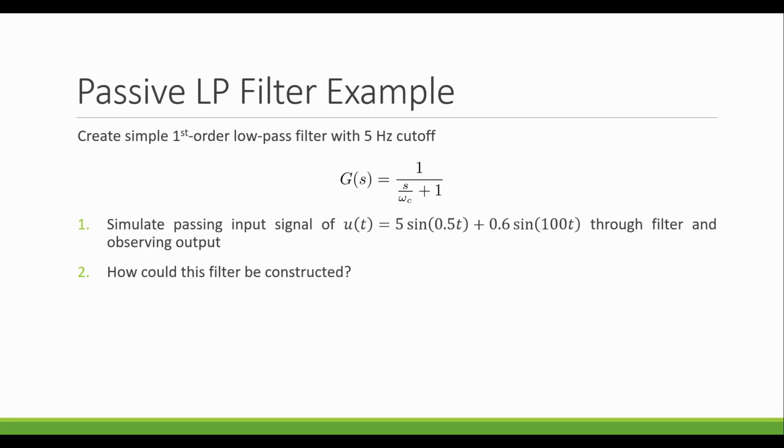A couple lectures ago when we talked about first order systems, I talked about how tau, the time constant, when we give it a step input, is going to tell us how long it takes to get to about 63% of the steady state response. But here, where we're going to be giving it a harmonic input, or we're going to see the sum of harmonic inputs, the tau, or really 1 over tau, is going to be the cutoff frequency.